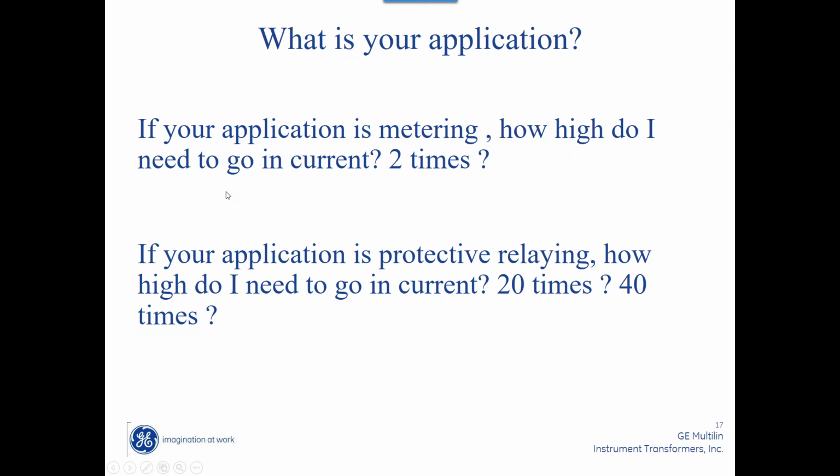Okay, what's your application? If your metering, there's 2 types of CTs you need to be aware of. There's protection CTs and metering CTs. And the question is, when do I use which? Well, with metering CTs, do I care about short circuit? No. With a protective CT, I better be concerned with short circuit.